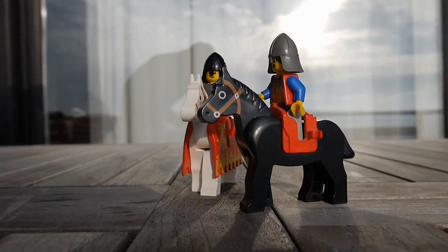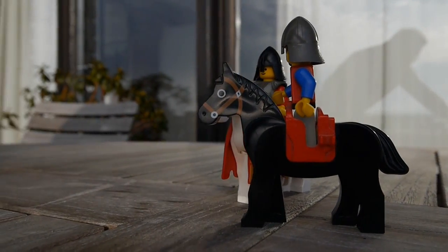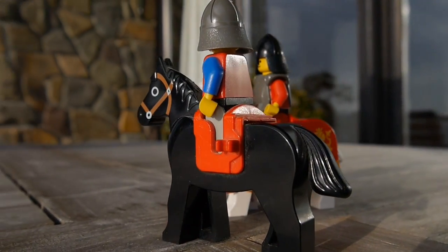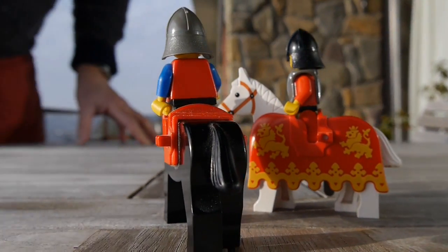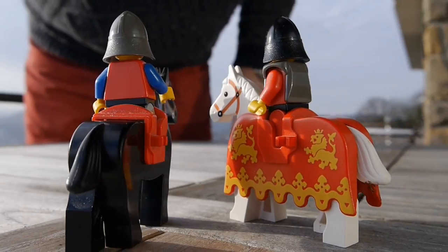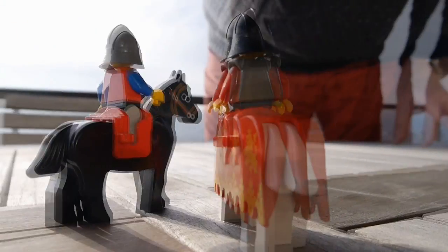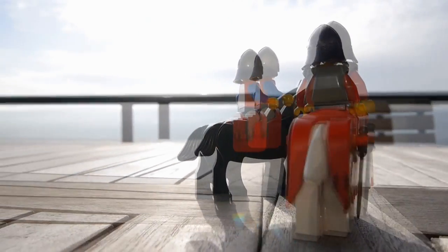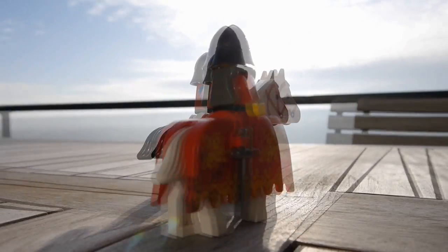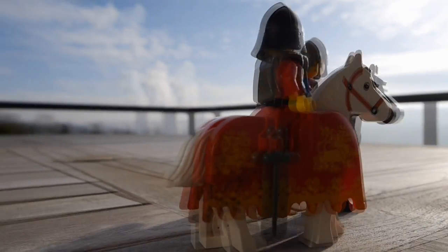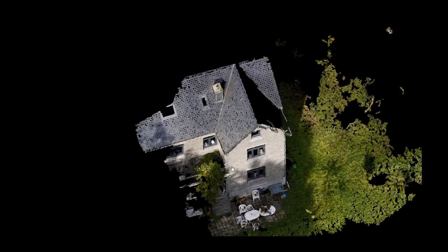The second approach is based on the analysis of 3D structure from motion. This principle is also heavily employed for 3D perception by human vision. Motion can concern the displacement of the viewing point or the displacement of the object or both. In this approach, a large number of images are acquired around the scene, and the software analyzes these images to extract the position of millions of points whose color is defined by the original image.